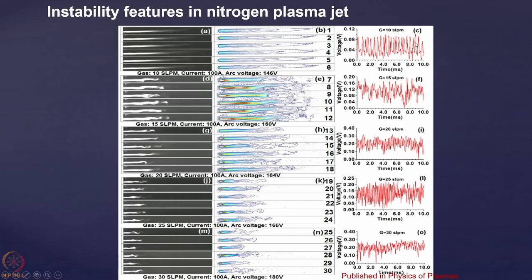the alternating component, what you are seeing in the voltage, the arc voltage, that you should look into. You see how the variation is occurring, and it is a sawtooth kind of behavior, a strike kind of behavior that you are seeing here, and the frequency of these oscillations. So there must be some frequency which may be giving a continuous kind of distribution, or a specific peak at particular points. So if you do a fast Fourier transform of the signals, then you will be able to know at what frequency these oscillations are happening.